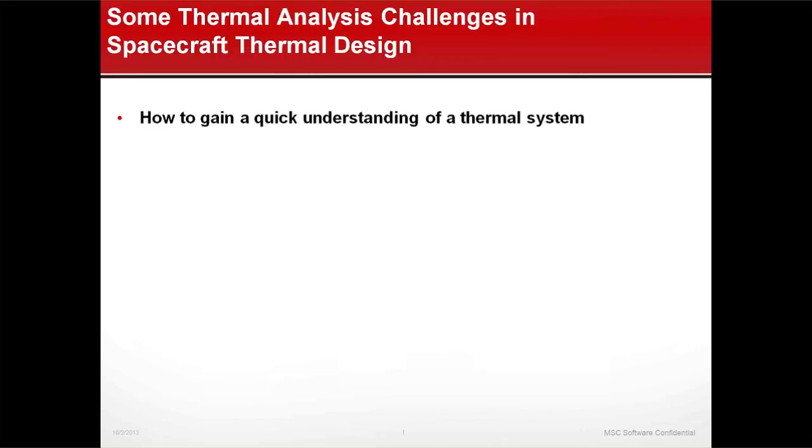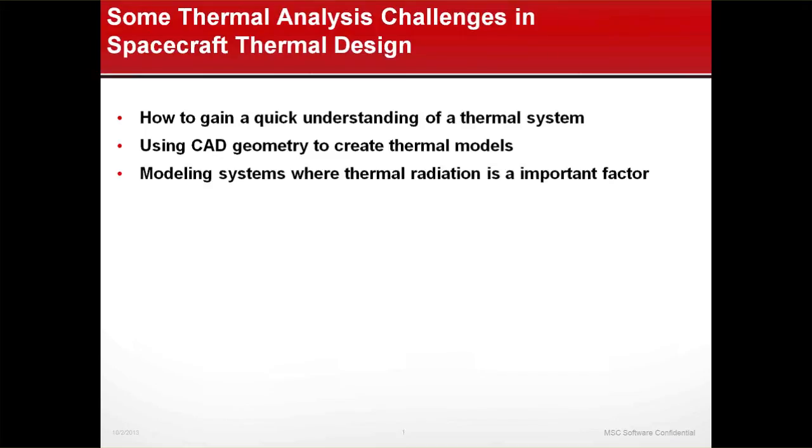So one of the things you want to do is try to quickly understand a thermal system. Frequently, you want to use CAD tools to create your thermal model. Modeling thermal radiation is critical for spacecraft thermal design, since that's how you get rid of your heat, and you get some heat gains also from solar loads. So having a variety of thermal radiation modeling features is important.